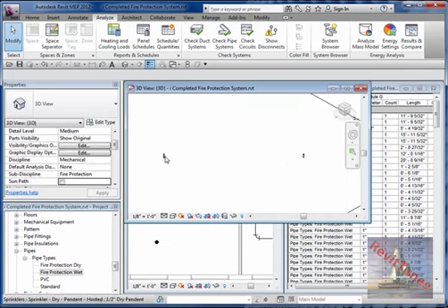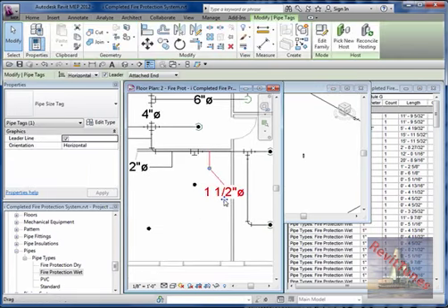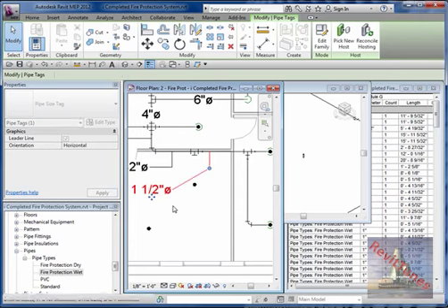Instead of changing to a wet system, I'm going to delete it, because the problem is, if I change from wet system to dry system, the pipes, the fittings, which are the elbows and the tees, don't go to the other system. Only pipes you could change from one system to another one. And probably I should have shown you that sample.